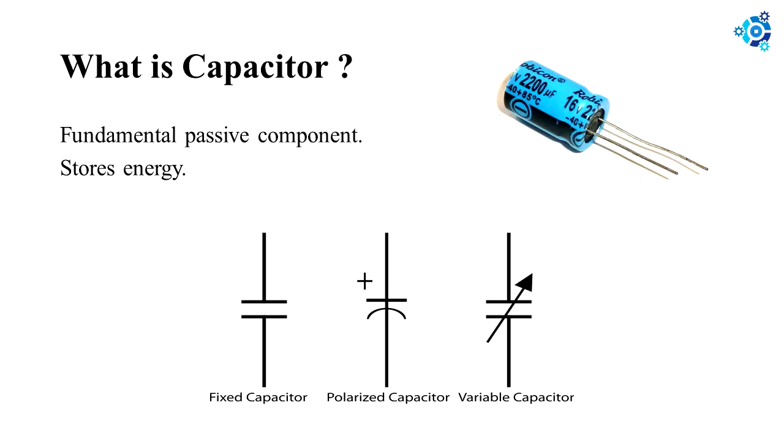The capacitor's symbol consists of two lines, which are either flat or curved. Both lines should be parallel to each other, close, but not touching, and this is actually representative of how the capacitor is made. The symbol with the curved line indicates that the capacitor is polarized, meaning it's probably an electrolytic capacitor. More on this will be discussed in the types of capacitors.